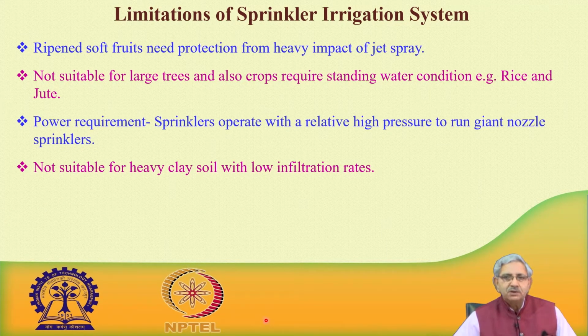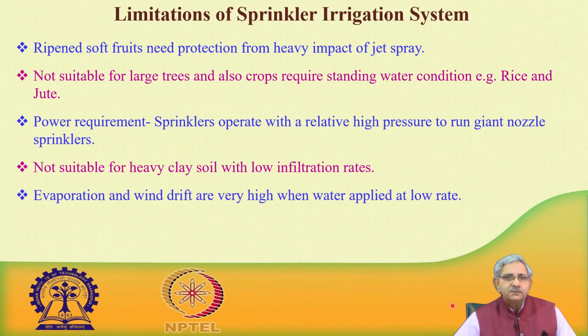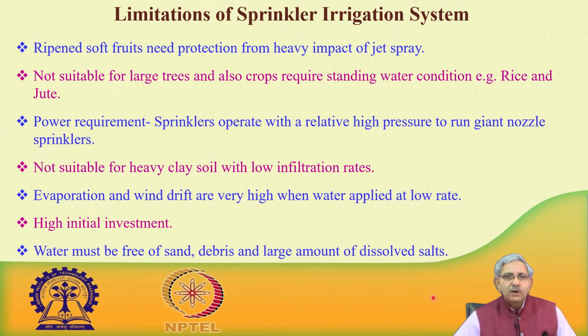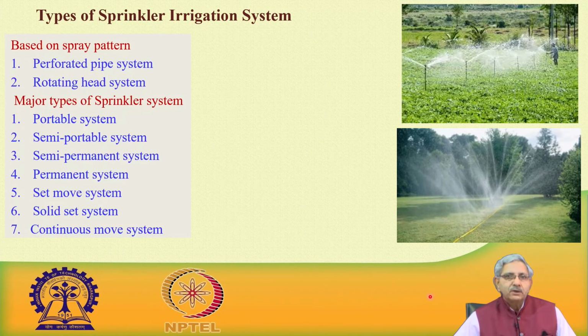One has to adjust the application rate for such soils, where the crops are grown in very heavy clay or fine texture soil. Evaporation and wind drift are very high when it is applied at a very low rate. High initial investment is involved, and water must be free from debris, sand and dissolved salts, because they may hamper the working.